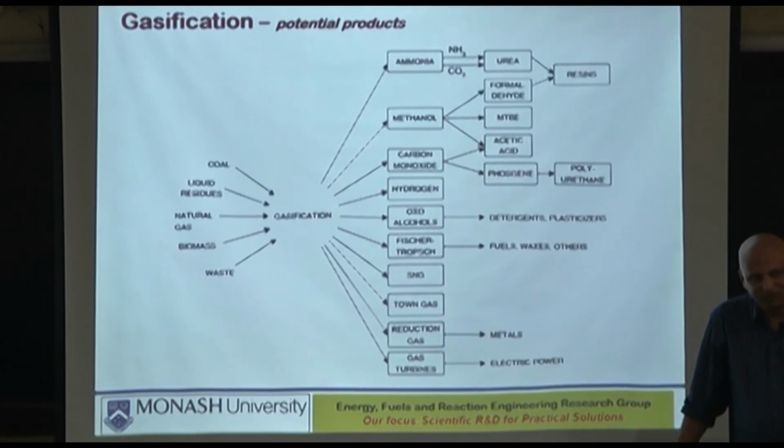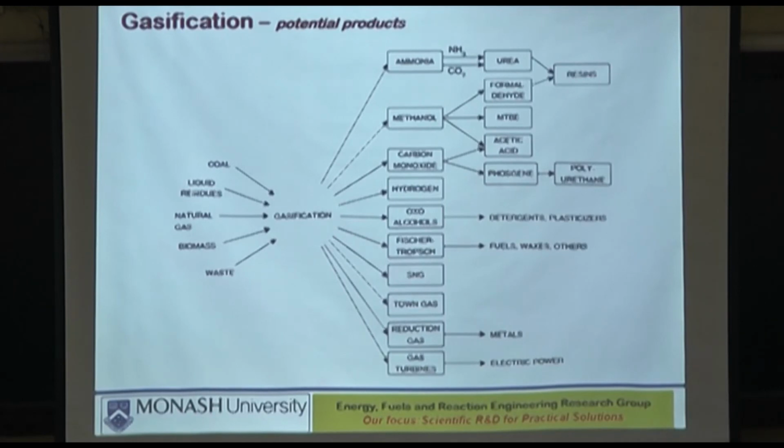Coal gas, petroleum gasifier gas, you get moderate pressures, 25 bar or so, below 30 bar, you will be barely getting 4% methane, not enough to do those sort of things. They are utilized to some extent, but that changes the dynamics, that changes the efficiency of the shift reaction and any other processes.